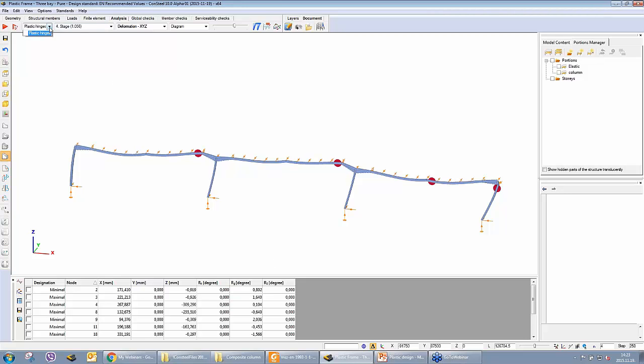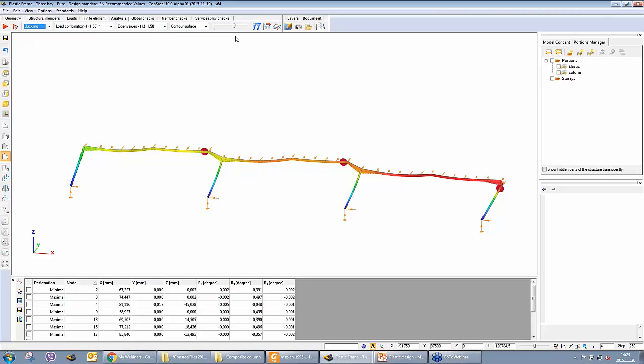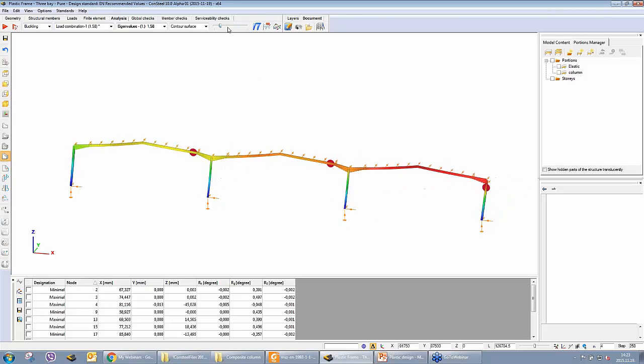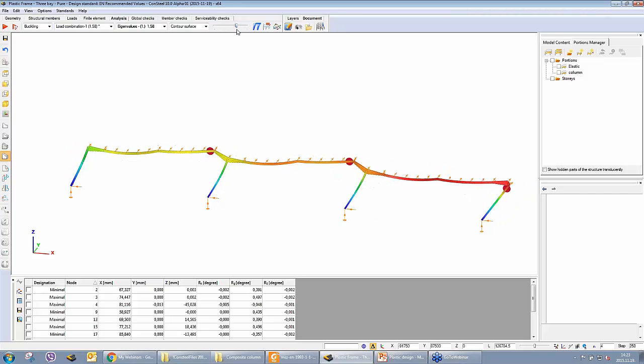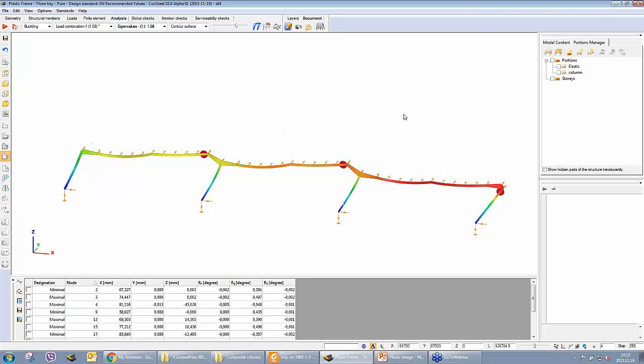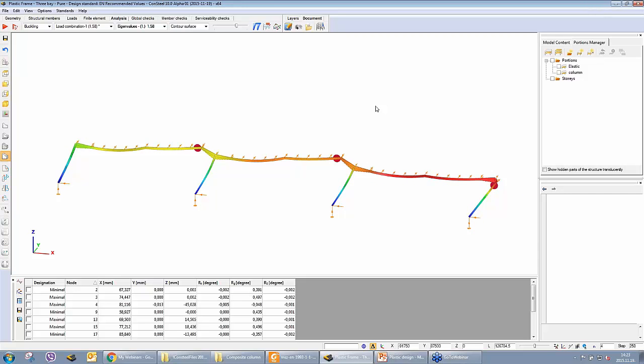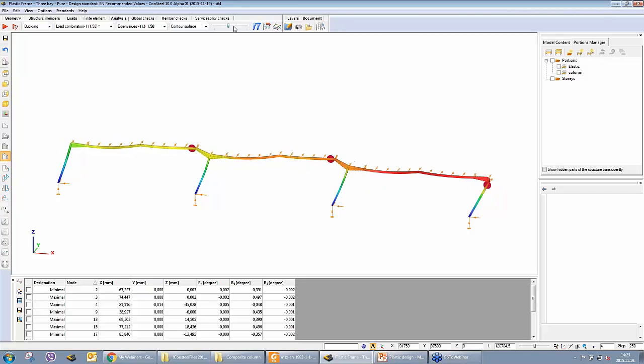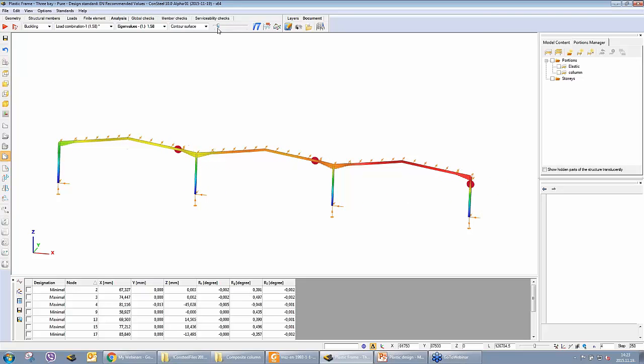If we look at the buckling results, what we see is that we have a different buckling shape now, which is dominant. This is the in-plane buckling, but considering the 3 plastic hinges which are relevant below the design load levels. If we have these 3 hinges, the in-plane stiffness of our frames has a much greater reduction.